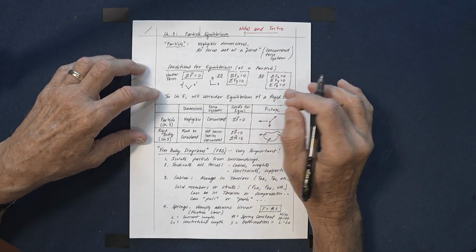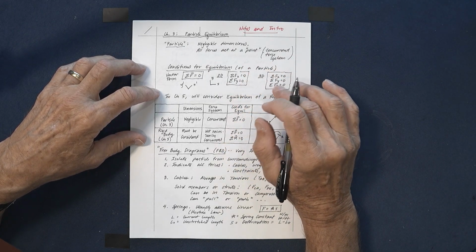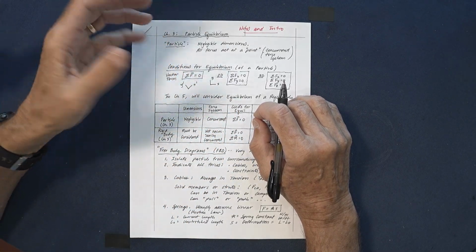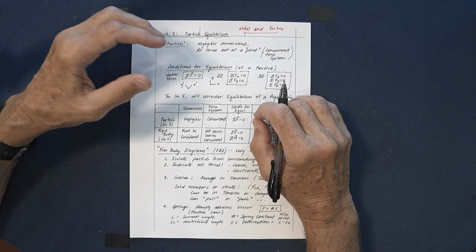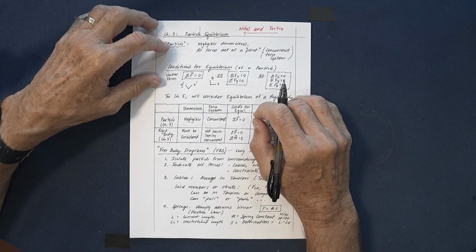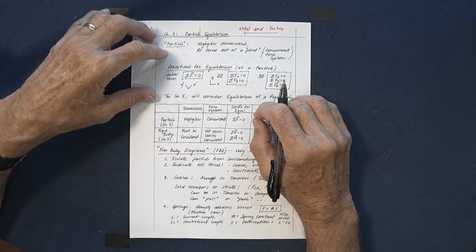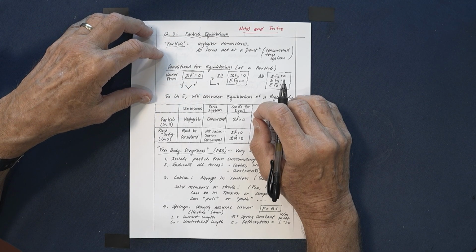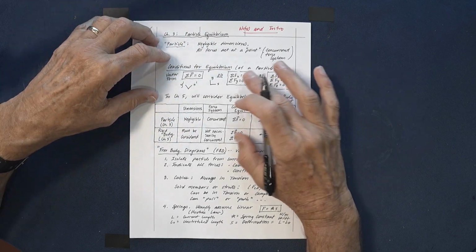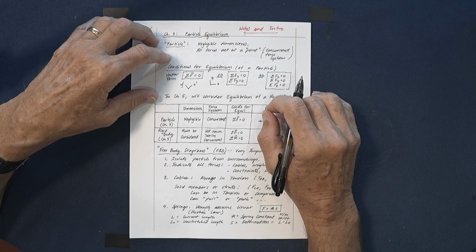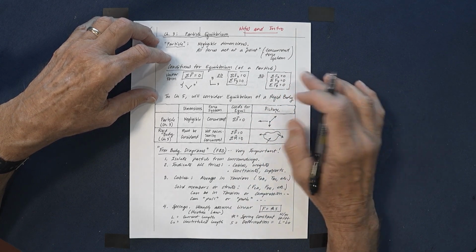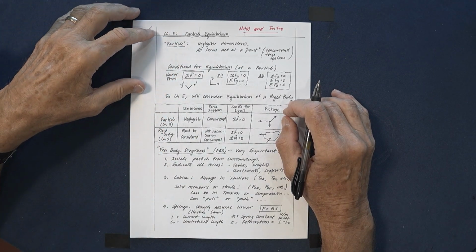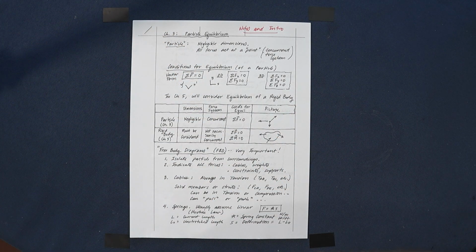One more thing about these conditions for equilibrium: because there are two equations in 2D, when I have a 2D problem, I can write two equations. But if I have three unknowns or four unknowns, and I just have two equations, then the problem becomes statically indeterminate. In other words, I've got more unknowns than I have equations, and I can't solve it. The same is true in 3D. If you have more than three unknowns, if you have 4 cables or 5 cables supporting, for example,